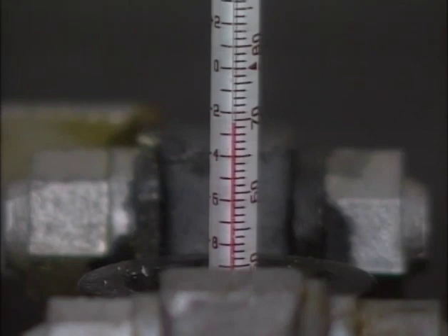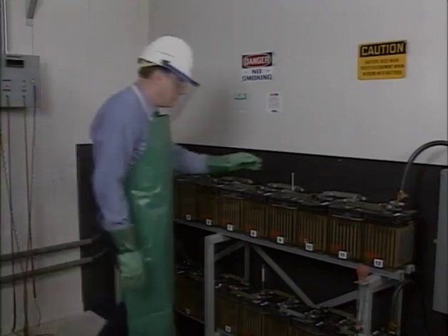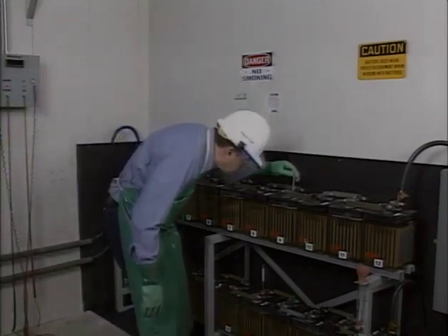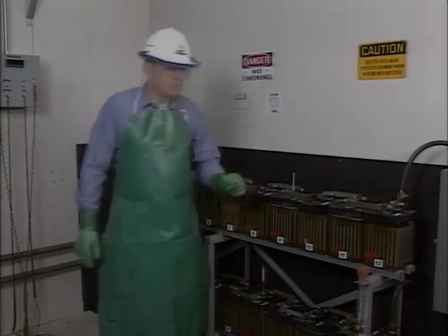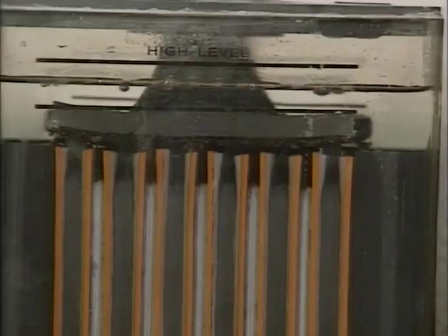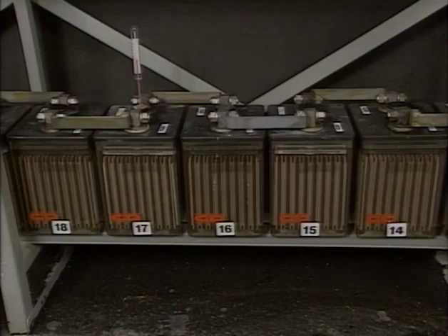During the equalizing charge, the same conditions are monitored that are checked during a freshening charge. The pilot cell temperature is noted regularly to ensure that it does not exceed the maximum allowable temperature, and the cells are watched for overflow or excessive gassing. If the temperature or gassing is excessive or if overflowing occurs, charging should be stopped until the cells cool to about 100 degrees Fahrenheit or 38 degrees Celsius. Then the equalizing charge can be resumed.